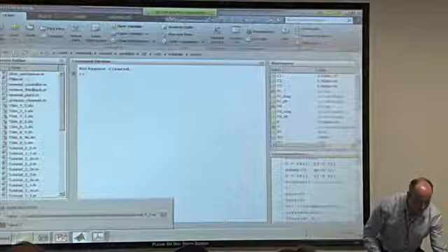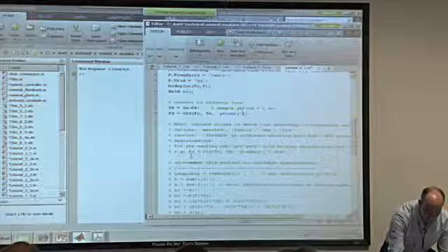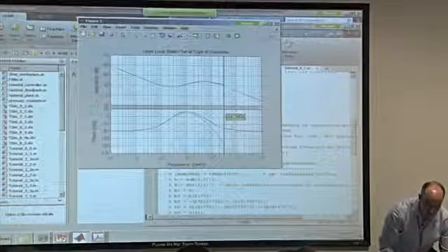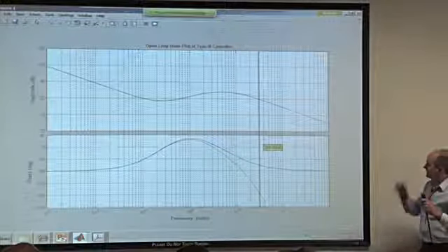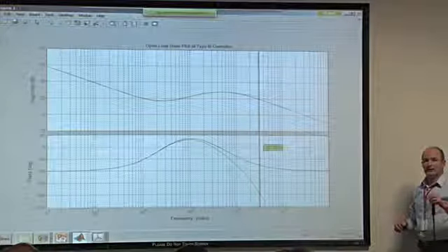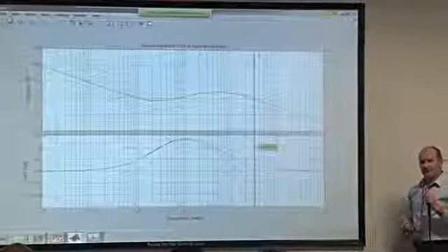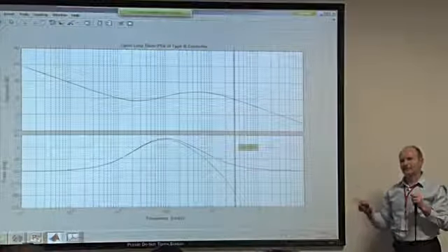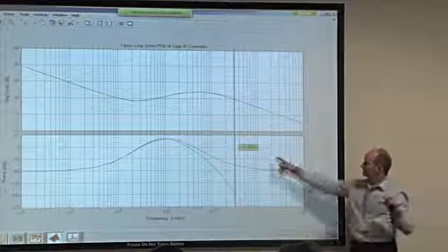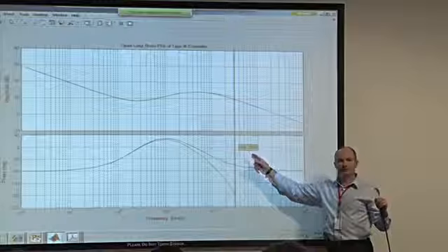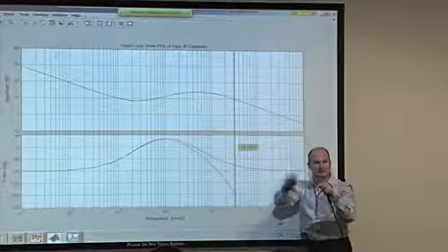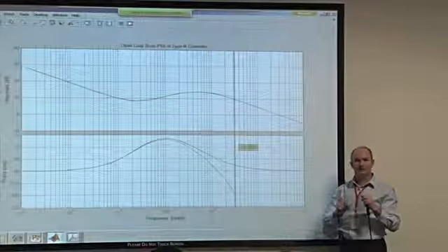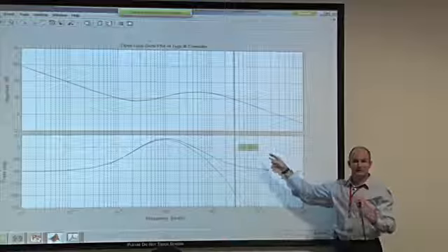In MATLAB, all we need do is replace the keyword with ZOH. And when we run this, this is what we have. Now, if this looks disappointing to you, it's actually not, because this is the most accurate of all the methods. The reason it's the most accurate is that when you build your system, you will really find this amount of phase lag, because this is coming from the zero-order hold, the thing that I approximated with that unit step, the difference between unit steps. That phase lag is genuinely going to be there. So this is true. This is what you're going to end up with.